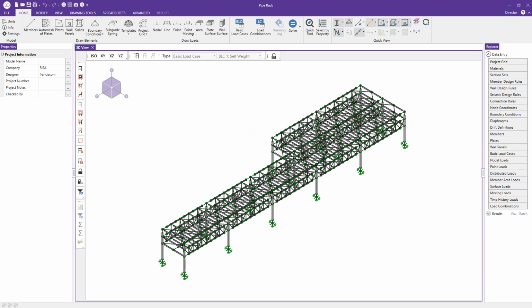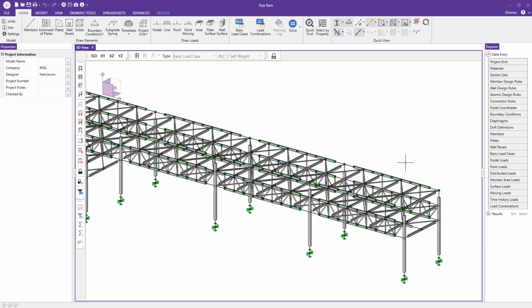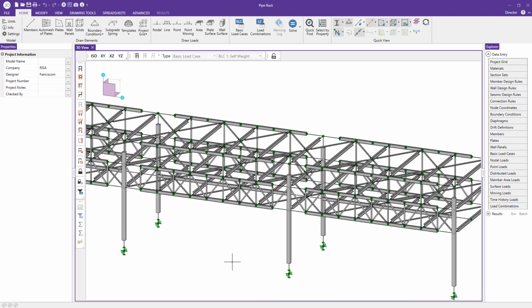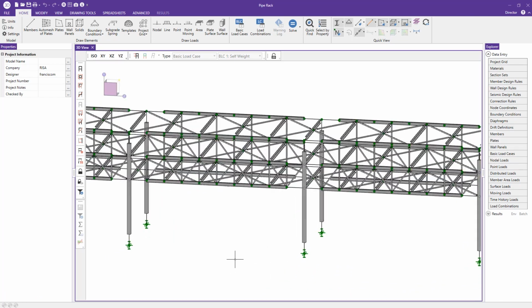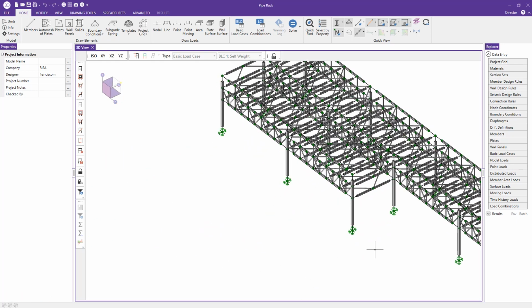And then as you see here, we have something actually quite similar to the image we were looking at in our PowerPoint. So we can pan around here. I can zoom in, and you can see we have essentially trusses that are spanning this long span from column to column. I've got some tube columns, and since we don't really have a diaphragm element, I've added a lot of horizontal bracing to give us a sort of pseudo diaphragm element. And so we can pan around, and you can see I just widened it to about 2 bays as you come down the length of the structure here.